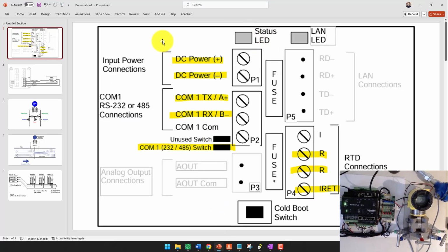So we could go and double check the connection that we have. Here's the back of the 4102. We are connected here to the SCADAPack 575. The positive goes to the positive and the negative goes to the negative on serial port 3 of the 575, and it comes in right here. We also have the power wired in, so it's powered up.